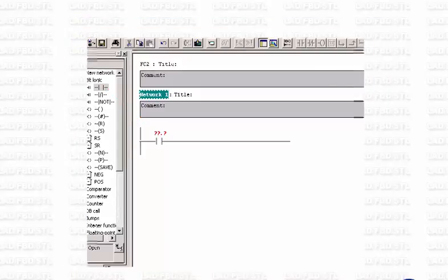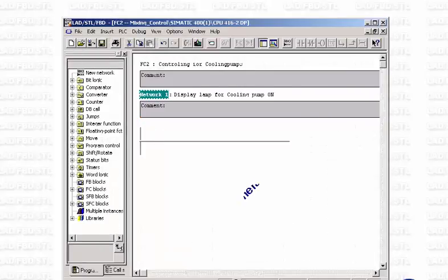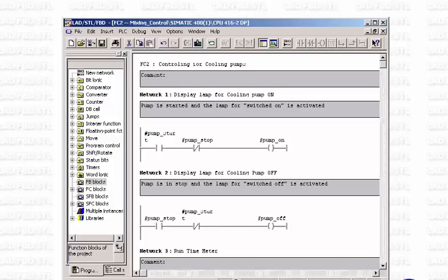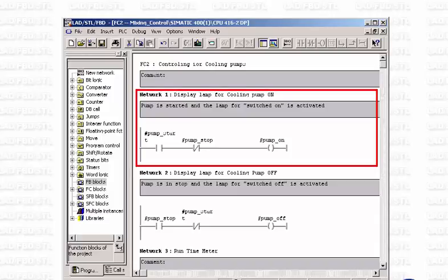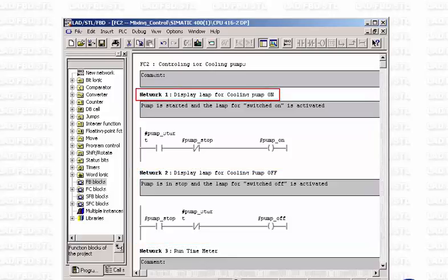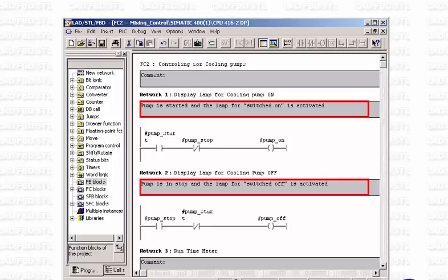or by double-clicking. To generate the program, the editor offers you a so-called program generation area. You use this area to structure and develop your program. The editor assists you, for example, by creating networks, which are self-contained program sections within a block. Each network can be given a title to allow quick orientation in very long programs. Moreover, networks can contain a freely editable comment in which the program content is precisely and exhaustively described.